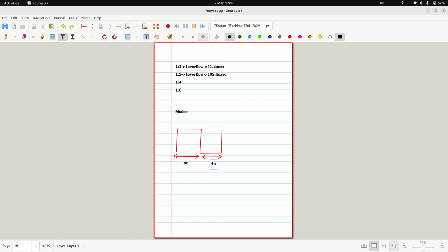What is the maximum value we can store in the register? That is 255. Here quantum is 1 microsecond. After how much duration is the interrupt generated? After 256 ticks. Each tick takes 1 microsecond, so 256 ticks take 256 microseconds. Okay, let me consider one example.